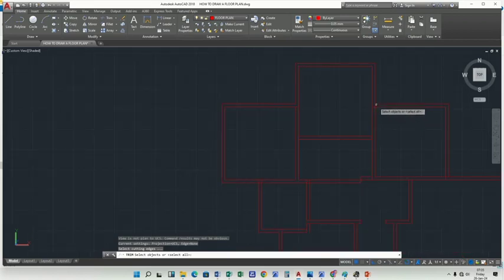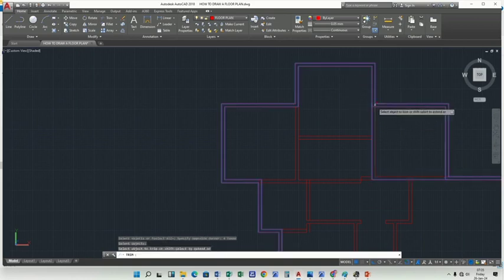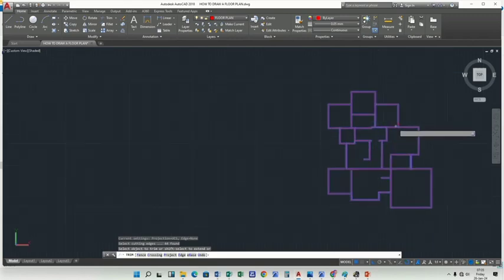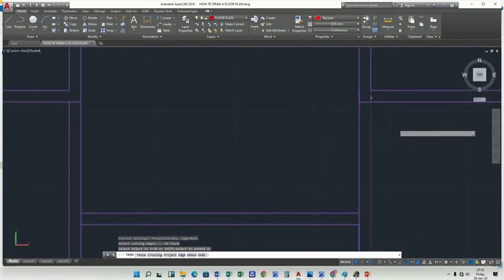This is how it's done. So I'm trimming there. Okay, trim. I'm cleaning the projects, select everything. Then I type TR for trim. Then I zoom in there where they are intersecting. I've clicked and clicked there.